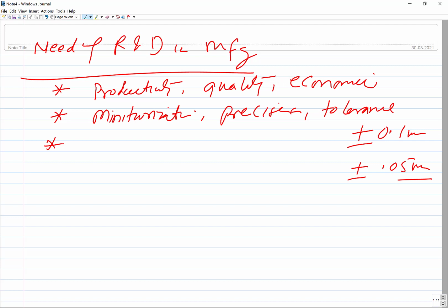Thereafter, with the development of supercritical thermal power plants, the temperature range increased from 550 to 650. With the further increase for ultra supercritical thermal power plants, temperature went further up to 750. You know, metals get weakened when exposed to high temperature, so they will not be able to sustain, and they will yield, deform, and fracture.